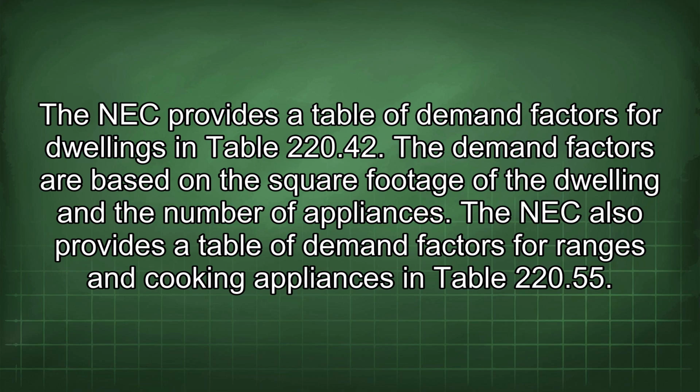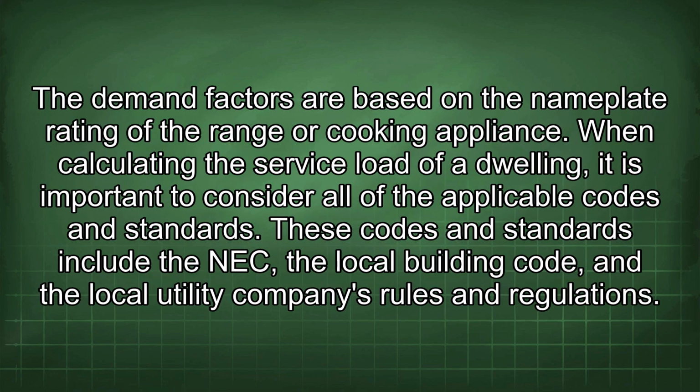The demand factors are based on the square footage of the dwelling and the number of appliances. The NEC also provides a table of demand factors for ranges and cooking appliances in Table 220.55. The demand factors are based on the nameplate rating of the range or cooking appliance.